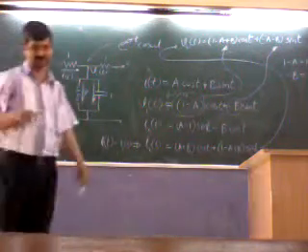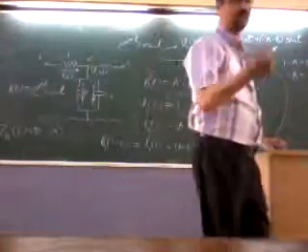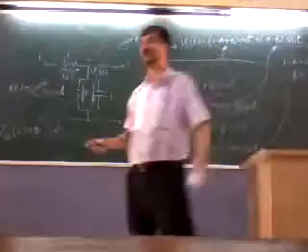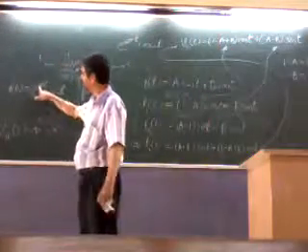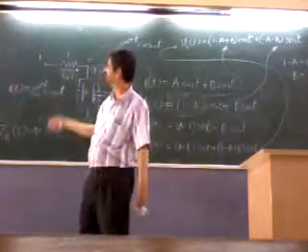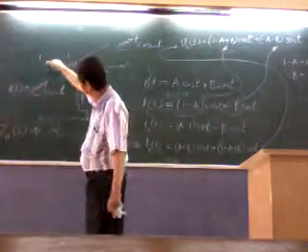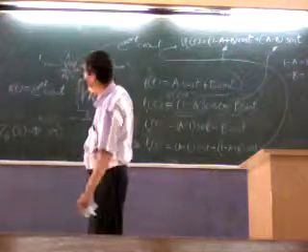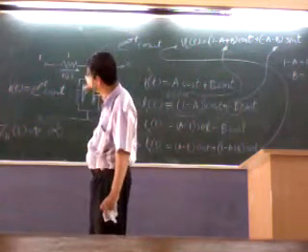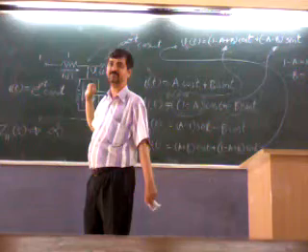Applying a voltage source and getting current to be infinite is difficult to derive. So apply a current source IT equal to e raised to sigma t cos omega t, then there will be some voltage, this plus this, and it will be such that their addition would be 0.